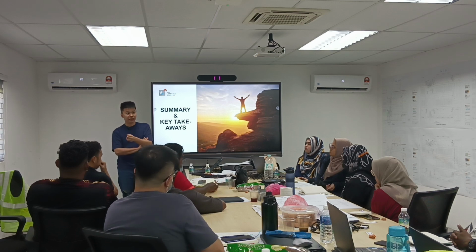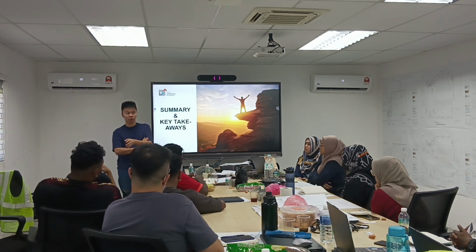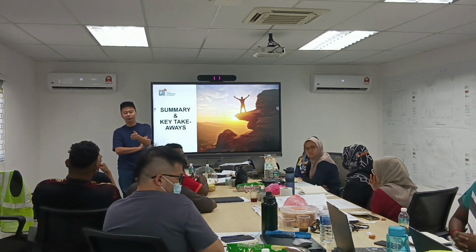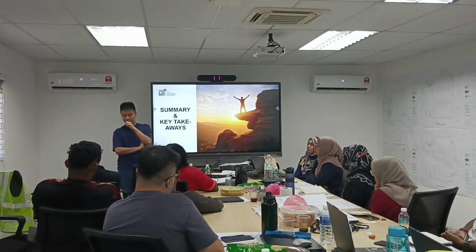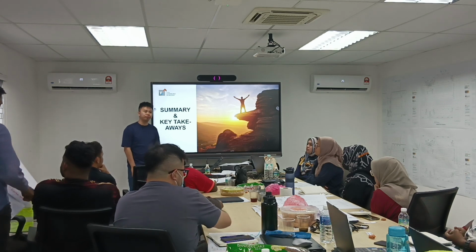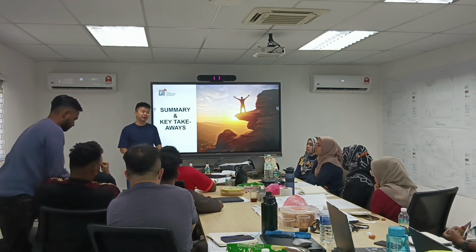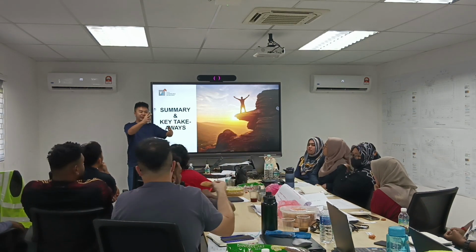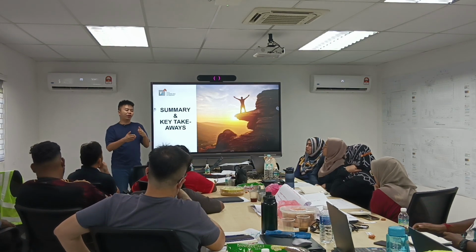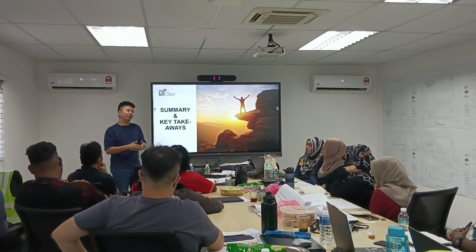Okay. First thing first. When we talk about tolerance, before we even touch the tolerance, you know that in building referencing, even your building reference point might have a tolerance issue, right? Means your building wall might also be running off. So first thing you should check is, is your reference point correct? Did the surveyor pack the correct reference point to you? Because when we draw the drawing, we don't assume the wall will be off, and you're taking two axes, X and Y. So when you say this is off by 50 mm, is it really the equipment off, or the wall off, or the column off? We need to justify this first.